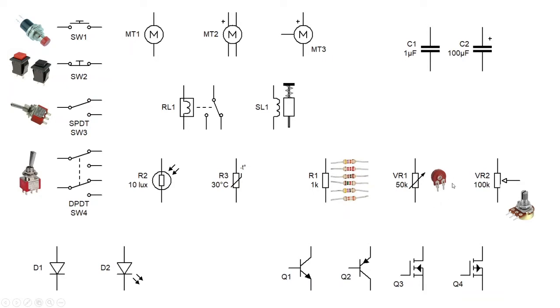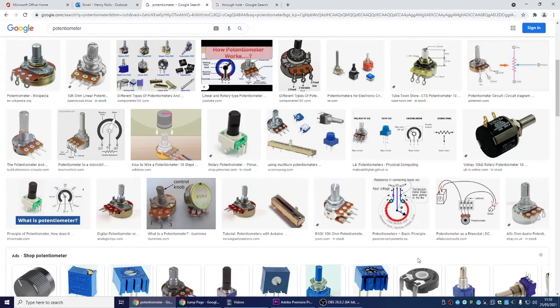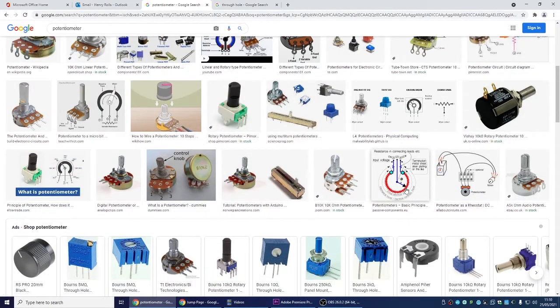Now these tend to be rare because generally you'll have something called a potentiometer, which has got 3 spades instead, or 3 pins. What happens here is you've got the full value of a resistor, say this is 10,000 ohms, across these bits. So if you connect the 2 outer pins like that, you'll get the maximum resistance that this thing is set at, often 10k they're called. And then the middle one is determined by turning this knob, and it's called a wiper, and it'll basically go from the minimum to the maximum range.